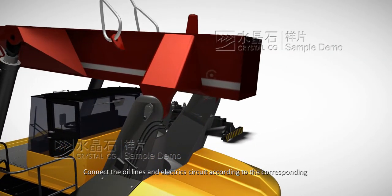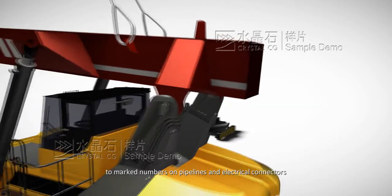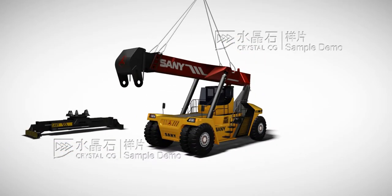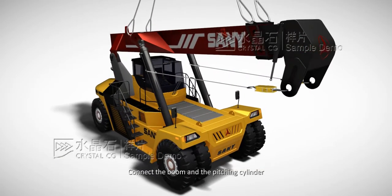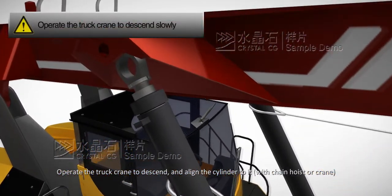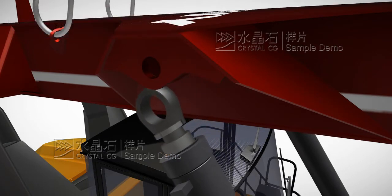Connect the oil lines and electric circuit according to the marked numbers on pipelines and electrical connectors. Connect the boom and the pitching cylinder. Operate the truck crane to descend, and align the cylinder to it with a chain hoist or crane.